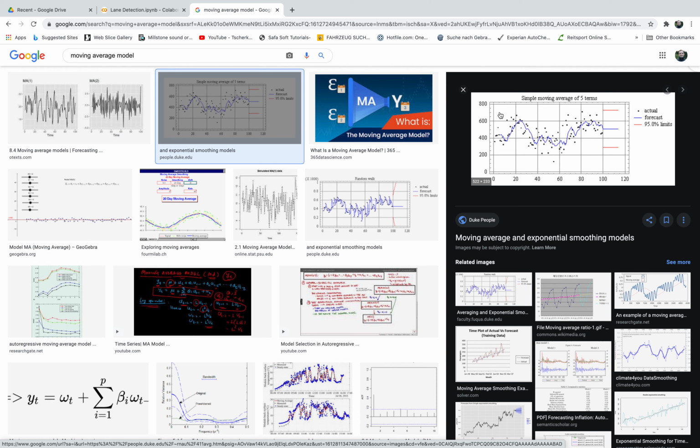If this coefficient is moving up or down like this, when we plot the lanes and also the curvatures, you can see that it has really high frequency and is changing really dramatically, and we don't need to have that as an input for our control system, or need a car to be very sensitive to that high frequency change. So by applying the moving average, we're trying to smooth and cancel out all this noise and just take the moving average trend of that.